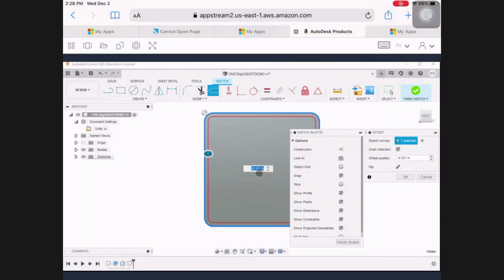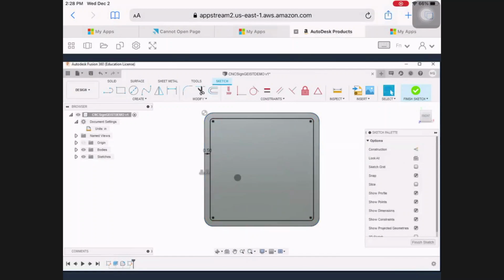And then I get a number. I can type in this blue area, negative 0.5. That's like a replicated geometry but on the inside. I'm going to press enter. So now you'll see it's duplicated, but 0.5 inches on the inside.